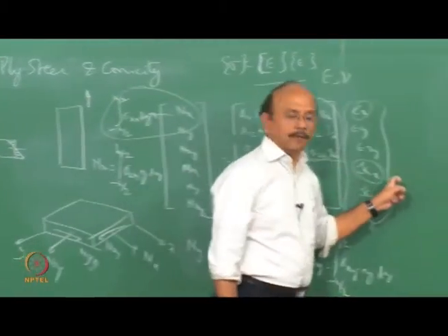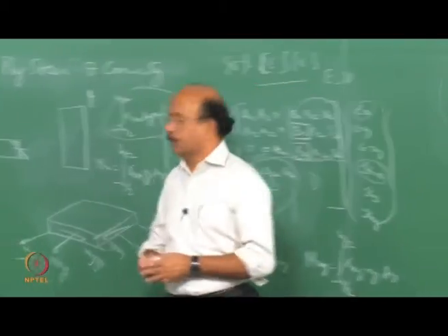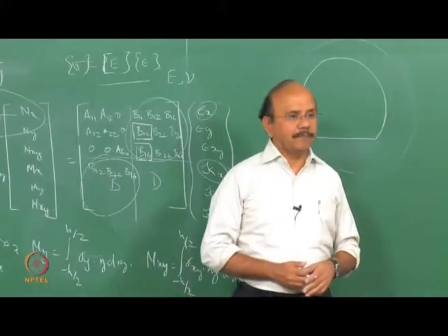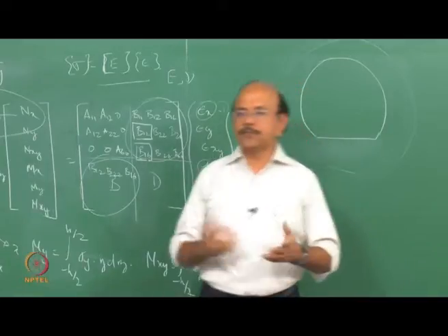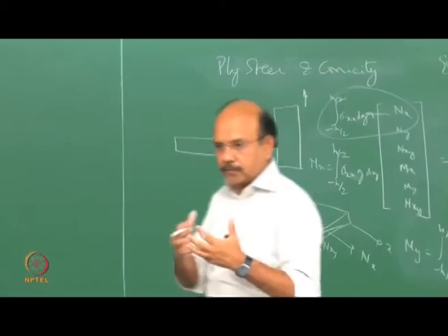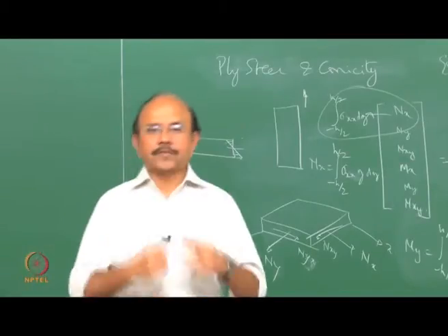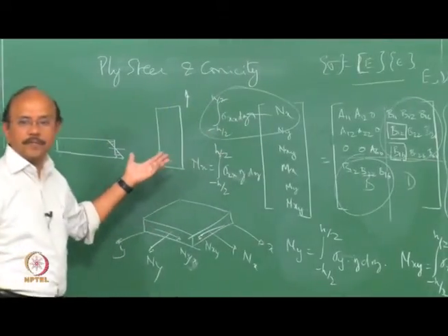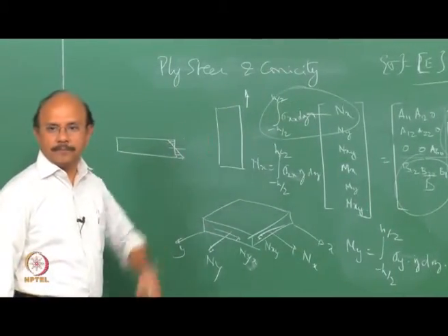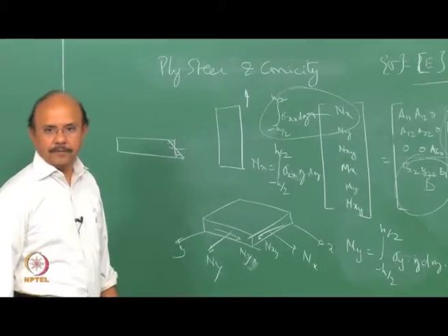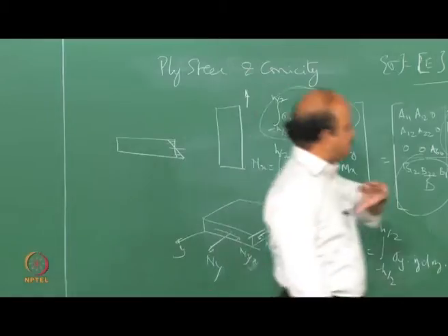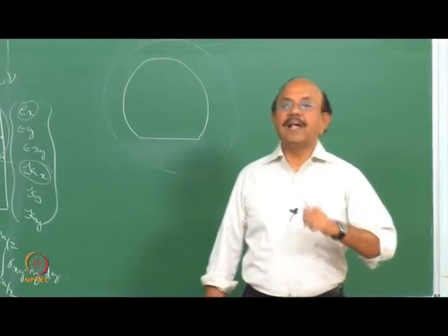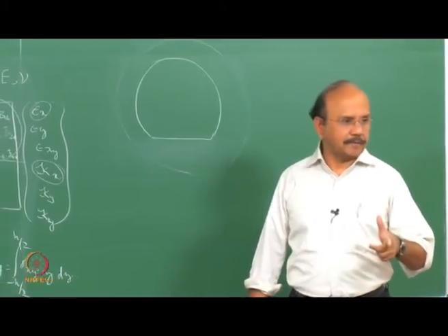There's a lot more to look at. So kappa x I'm going to change now because I'm going to make it flat. When I make it flat, obviously I'm introducing forces, because of this coupling term. And those forces introduce the lateral force and a moment. So the simple fact that as the tire rolls on the ground and a part of the tire becomes flat results in a lateral force called ply steer.